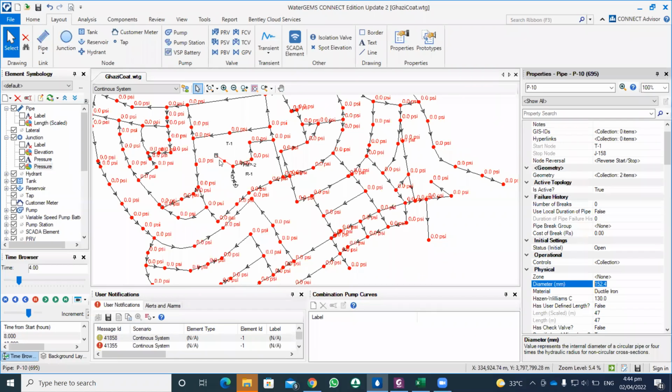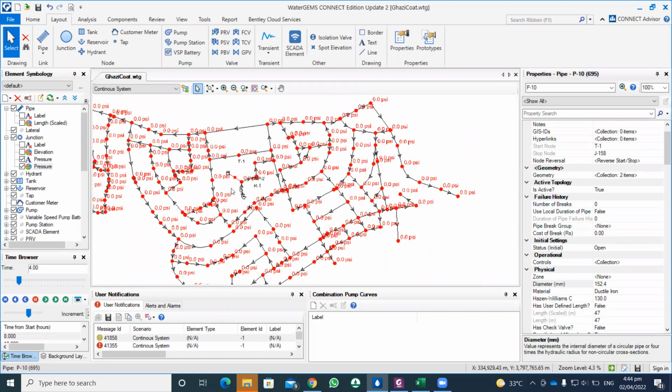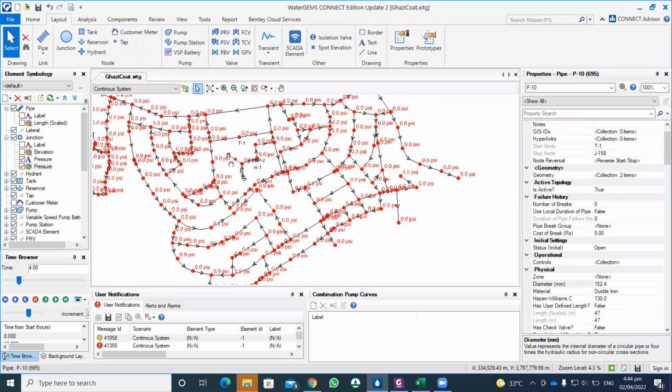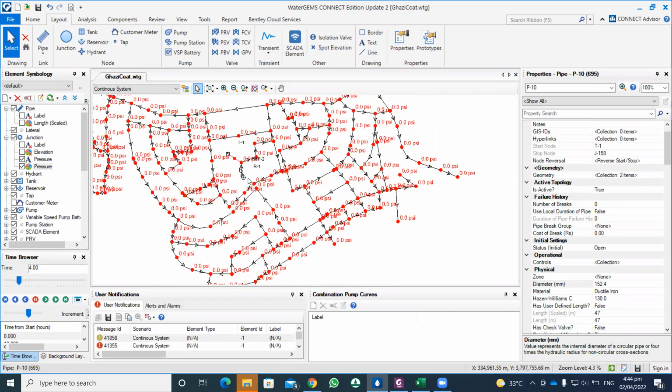So I will just show you one pump, one tank, though I think for this system one tank will not be sufficient to fulfill the demand, and it is not appropriate to use such a high pump for that system. So you should use 2 or 3 pumps if available, of low discharge but giving a high head of water.